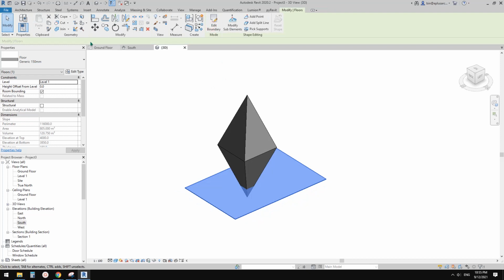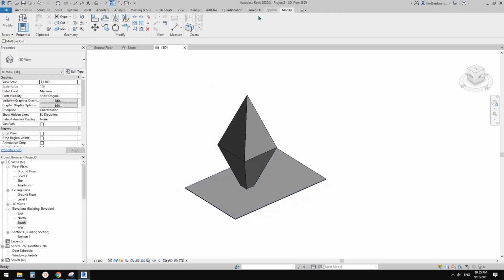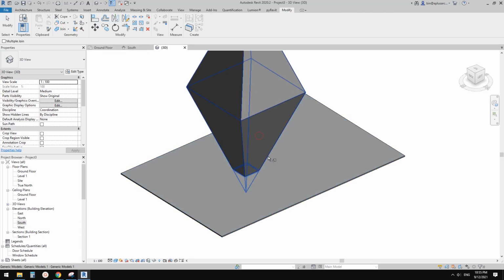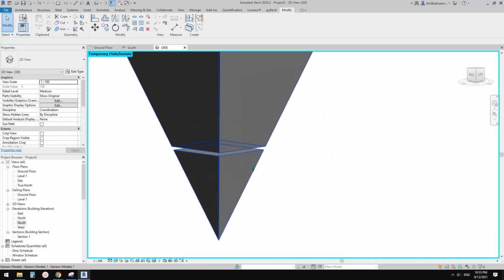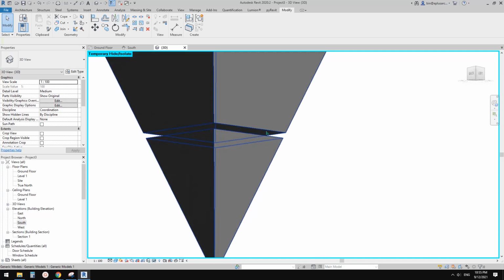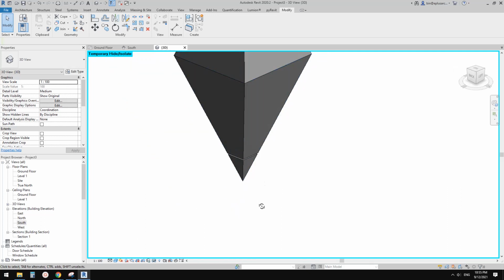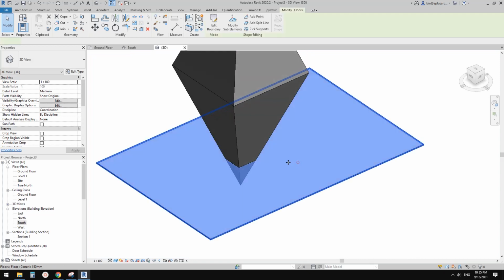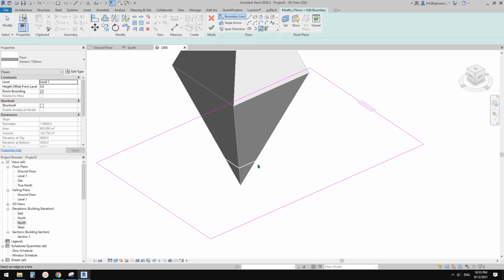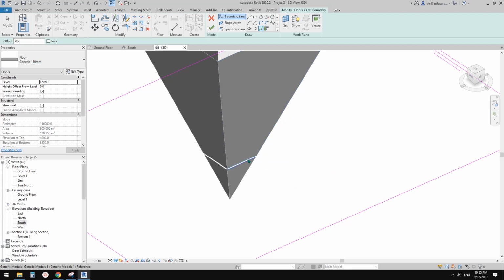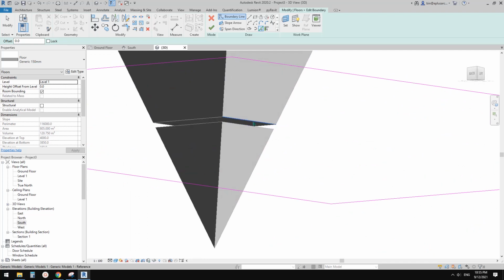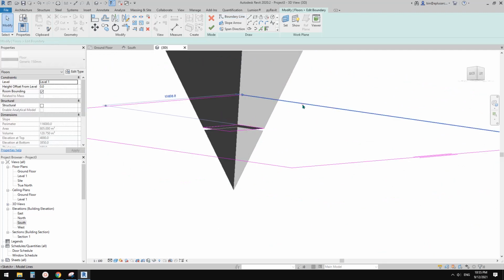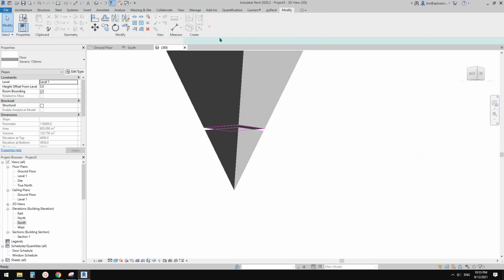Finish. Okay, and then I'll use the join tool. On the modify tab, join. Pick this floor. Pick this generic model. So now if I hide this floor, you will see we have this edge. Okay, now let me just HR, select this floor, edit boundary, pick line, tab, tab, tab. I can't pick tab. Yeah, okay, all good. And then just delete this, finish.